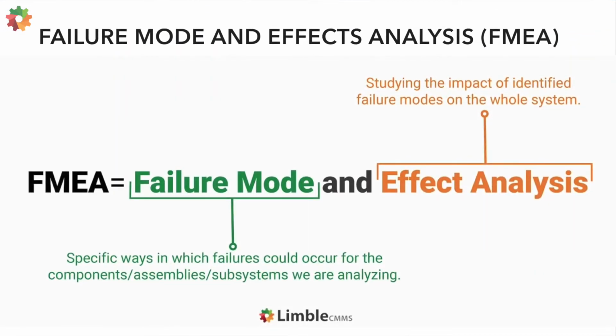Failure mode and effects analysis combines a systematic approach of reliability engineering, safety engineering, and quality control efforts. It tries to predict future failures and defects by analyzing past data. A diverse cross-functional team is essential to undertake this type of analysis. Because each subsystem design and process must be questioned, failure of similar processes and products in the past can be analyzed to supplement the process.